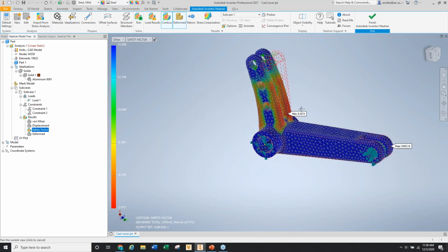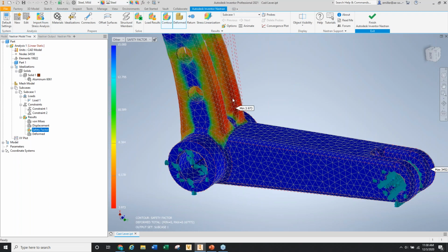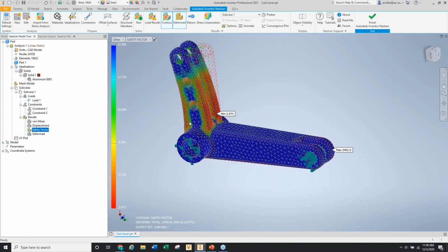At that point, maybe I go back and ask, can we take out some more material, maybe turn these holes into slots and not worry about cracking, if we're concerned about the amount of weight or material. The more we do 3D printing, if it's a small enough part, we could easily make it that way instead of doing a full cast, depending on the type of material. And obviously instead of aluminum, maybe we'll use a composite.